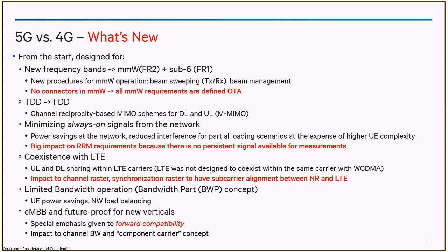Apart from that, 5G initially started as a TDD-only technology, but then because of the push of certain North American carriers, FDD was added. But the physical layer structure is still very TDD-centric. It allows switching between downlink and uplink inside one single millisecond.